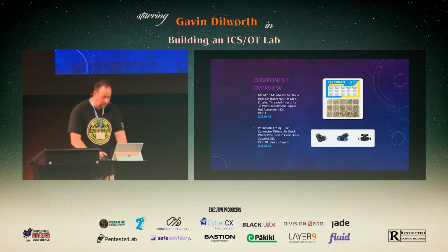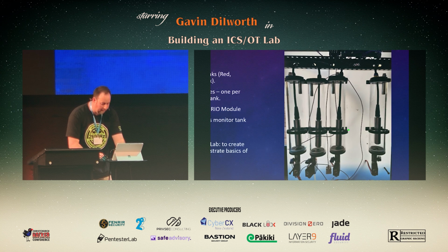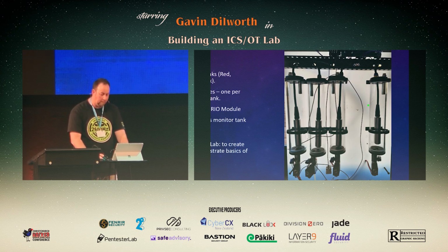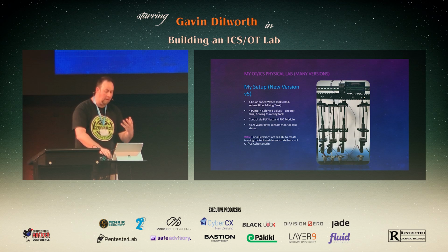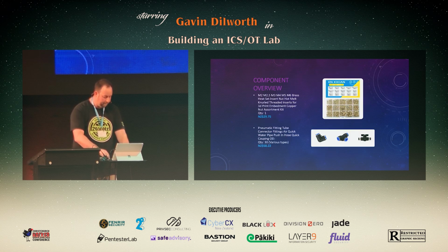These inserts, so if we go back to the version 5, every screw that's mounting, you can see there, this cable tray is mounted. There is a threaded insert behind it, okay, because what's on the back here is clear perspex, or misty perspex, and you don't really want to be drilling, there's a chance of cracking. So you generally put in a pilot hole and then you get the threaded insert in, and it holds it quite firmly. So that's another piece of the kit.